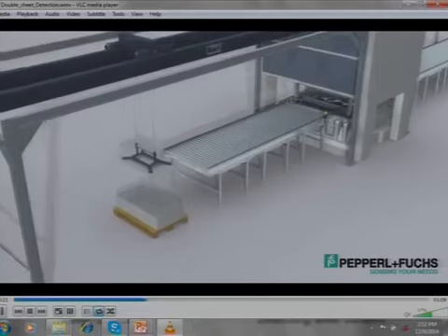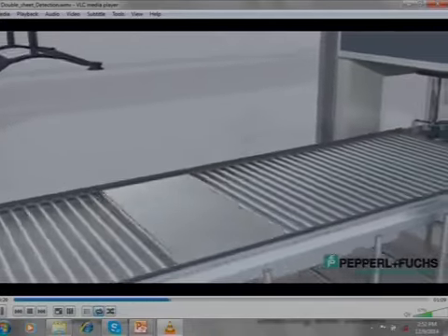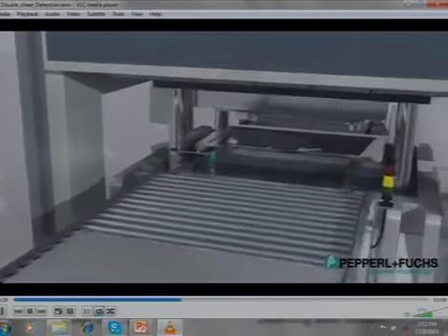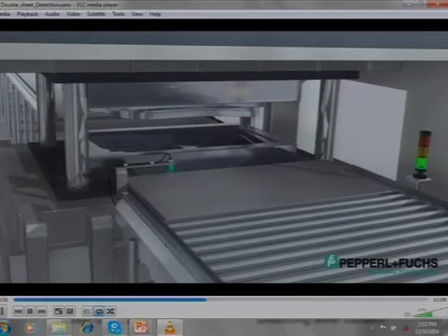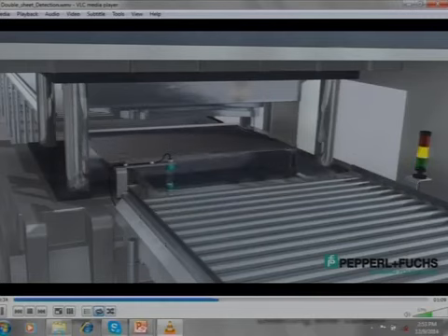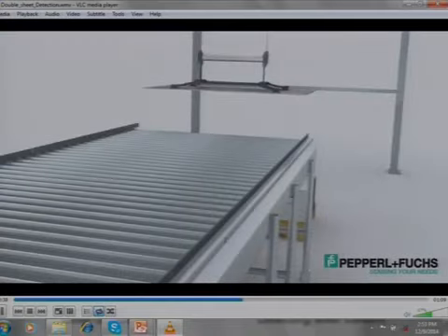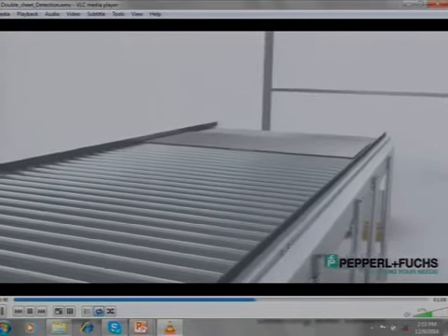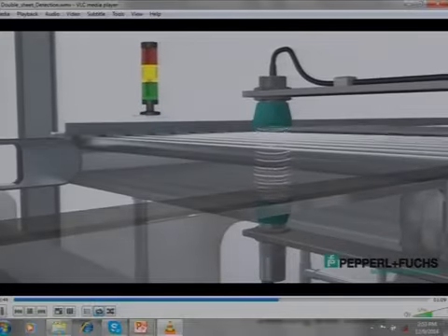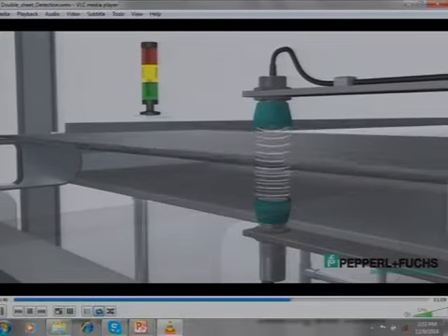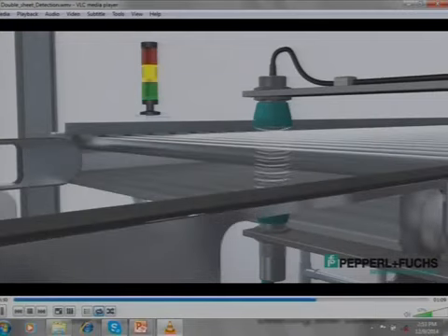Can there be any circumstance where there is a false alarm also? Any exceptional case, for example, where there are not actually two sheets? I have come across some applications where this has happened. It was because on all of the sheets they put a lamination, and the lamination was not uniform. There were certain air gaps inside it, and as a result of those air gaps, it was always detecting two sheets, even if there was a single sheet. So certain limitations are always there.